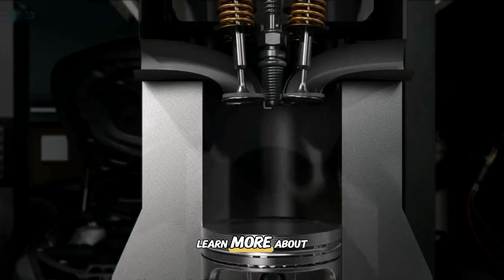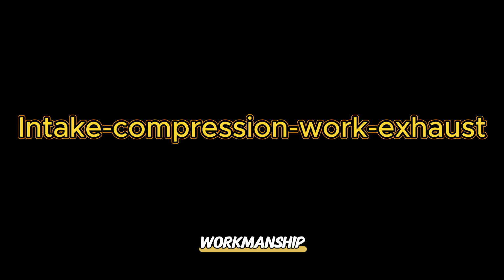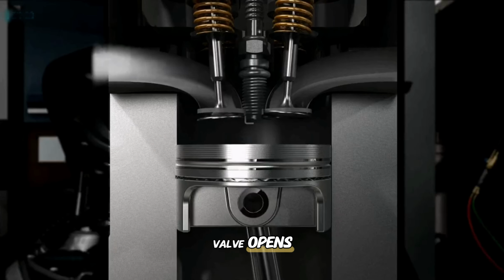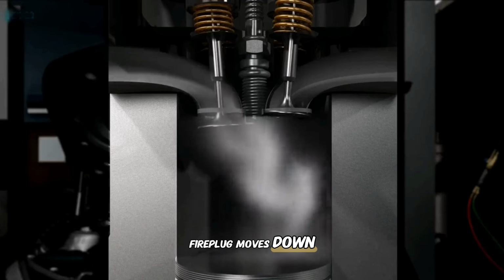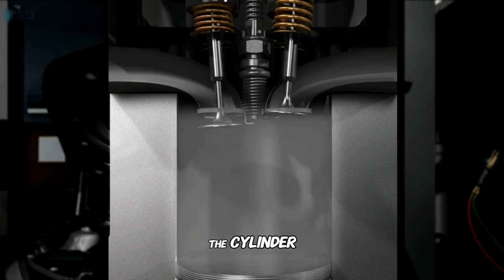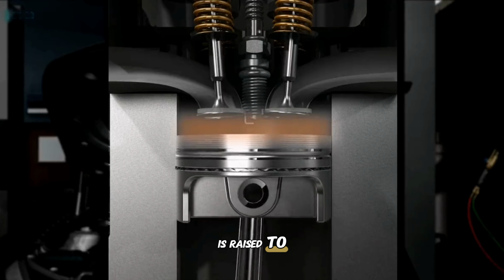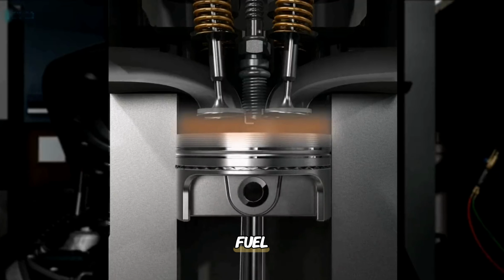Next, we will learn more about the 4-stroke cycle. It follows the intake, compression, power, exhaust cycle in sequence. First, the intake valve opens, the piston moves down, then a mixture of air and gasoline is sucked into the cylinder. This is the intake stroke. The intake valve closes. The piston rises to prevent it from further inhaling the fuel.